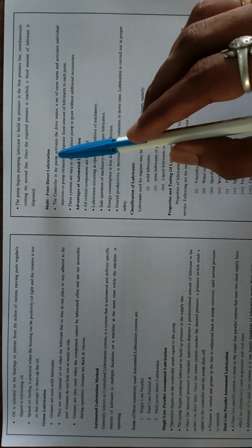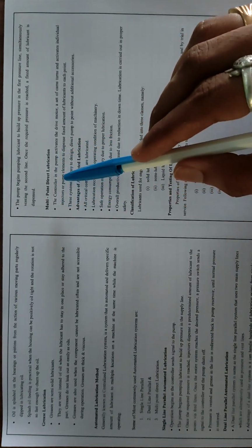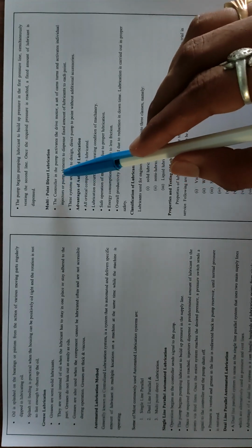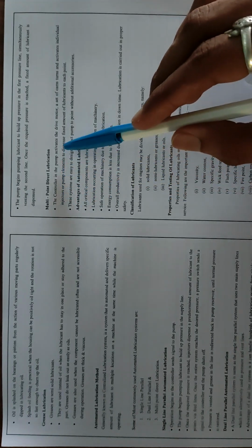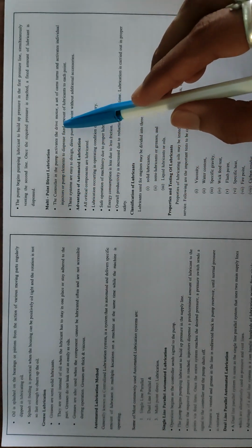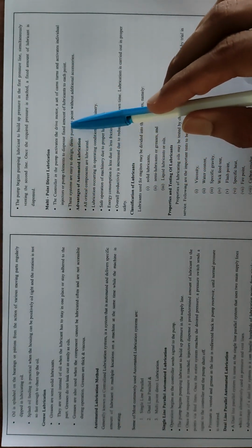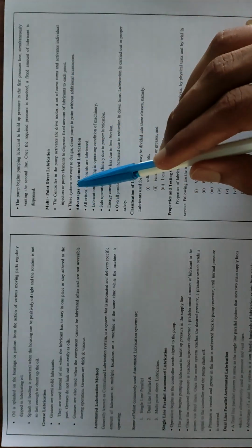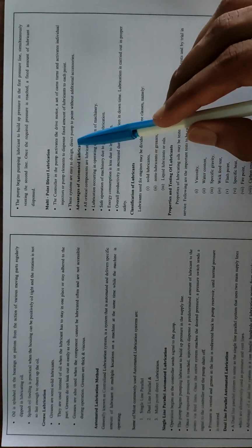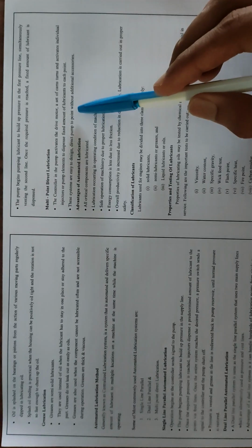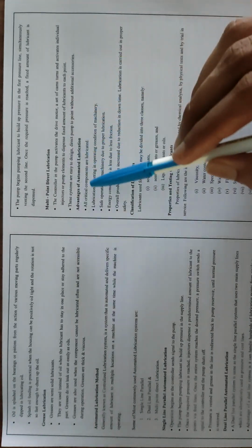Multi-port direct lubrication. The control in the pump activates the drive motor. A set of cams turns and activates individual injectors or pump elements to dispense a fixed amount of lubricant to each point. These systems are easy to design, direct pump to point without additional accessories.